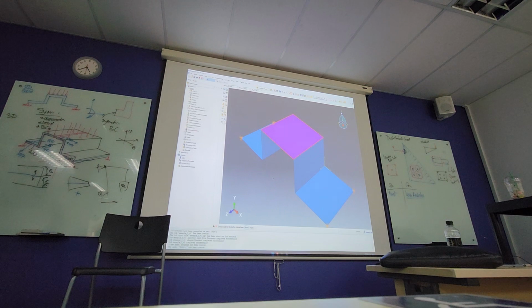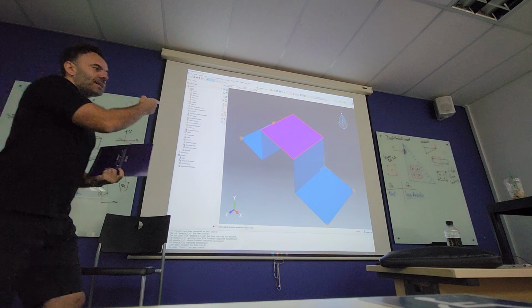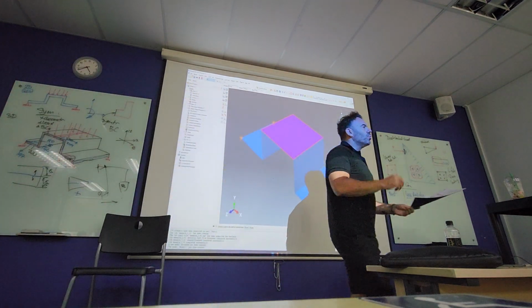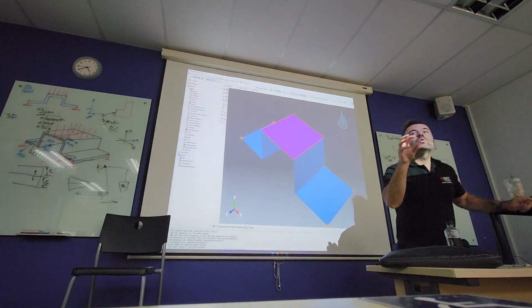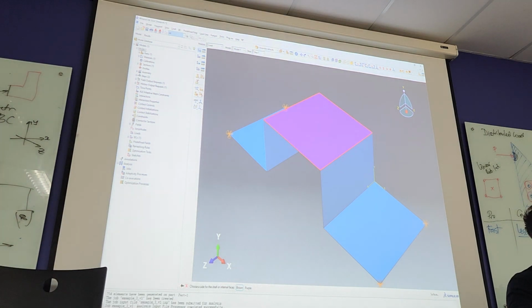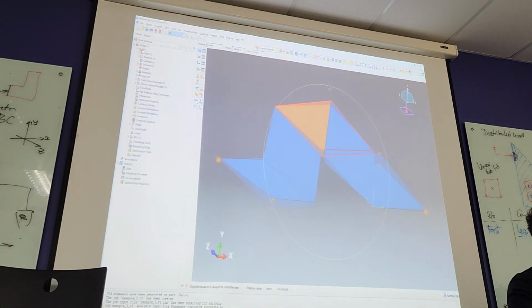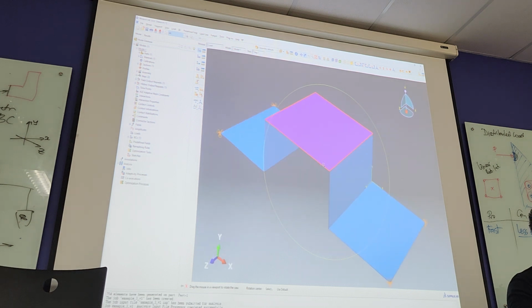But when you have something that doesn't have thickness, when you select that, you don't know which side you are selecting. A surface does have sides. So that's basically what's telling us here. Where is that side that you want your pressure on? Is it going to be this purple side or the bottom, which is brown? So you have to choose. Yeah, for us, we want purple.